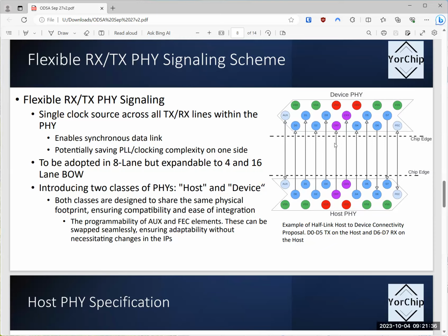Sorry, I didn't understand. This is when this is working with a normal file? Yeah, the default one, and then this special 4-bit mode, you actually have the TX shift half cycle, right? Then I cannot just say it's a half cycle shift, it's a guarantee. I need to ensure the setup and hold margin is sufficient, with the skew in the timing sign-off as well, just like the way our DDRs are checked.